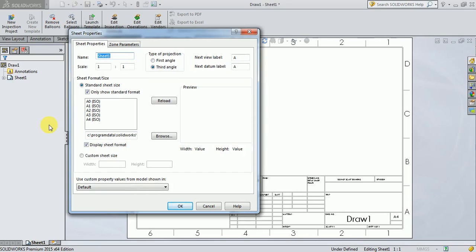As you have already learnt in your machine drawing, in India we are going to follow the first angle of projection, which means the front view will always be above the top view, that is, below the front view we are going to get the top view. Above the XY line we draw the front view, and below the XY line we draw the top view. That is first angle of projection: the object comes in between the observer and the reference plane. That is what we are going to follow.